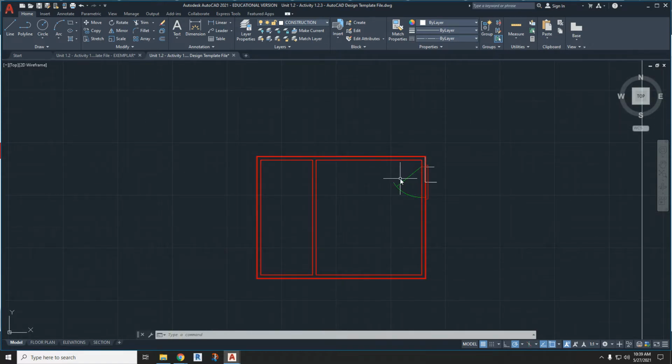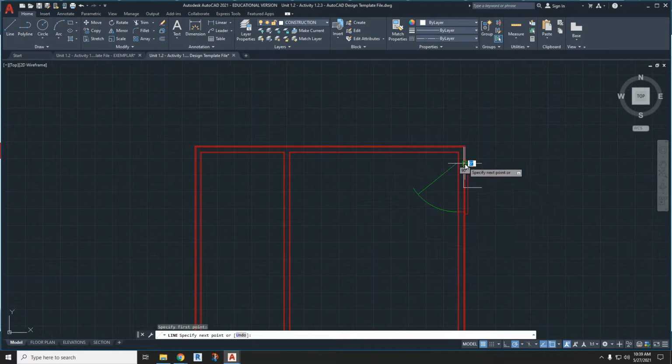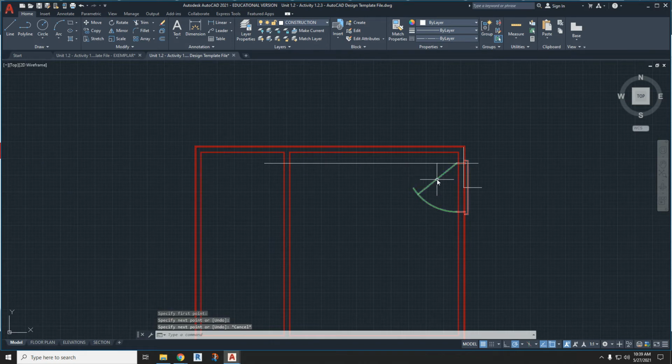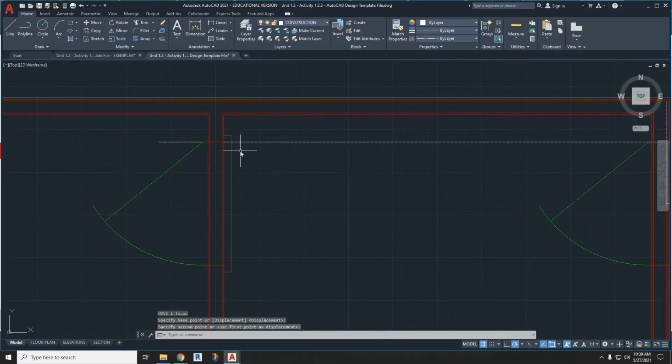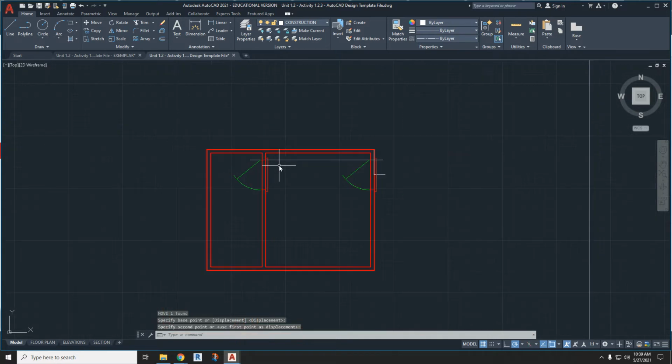I will have another door here. So easiest thing to do, if I want to make it nice and symmetric, is to copy and paste. Highlight, hit M for move, and then move that to right there. Okay. And now let's put in some windows.